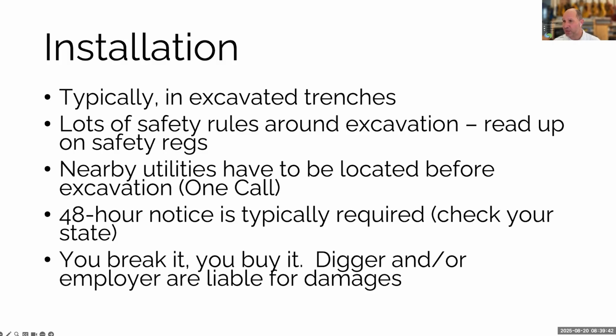Typically, it's 48 hours notice. Again, this is something that varies by jurisdiction a little bit, but this is more a practical day-to-day operations issue than a test exam example. But you're typically going to need some 48-hour notice. And again, it's one of those things where it's you break it, you buy it, and not only is the company that did the damage liable to be on the hook, in some cases, the person doing the digging can actually be personally liable. So when in doubt, ask. Good thing to pay attention to.